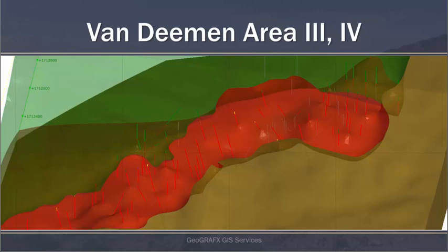We started out using only the surface geology and drill holes to create the model. We did include strike and dips from the historical mapping. We then cut sections along the same section lines as the four historical sections we had previously recovered. The results showed marked dissimilarities in contacts between the units. To resolve the discrepancies, we digitized the boundaries on the sections back into the model. The result was more in line with what was encountered in the drill logs, sections, and diagrams in the reports.